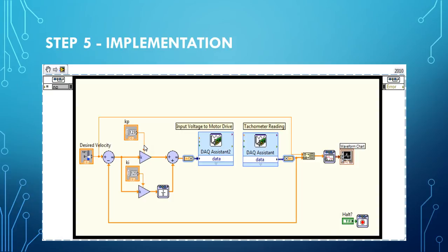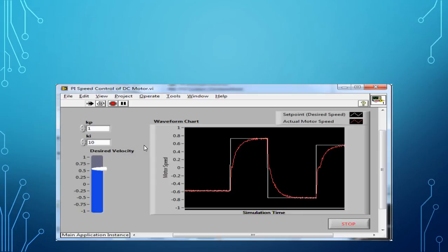Timing is an important consideration when using the LabVIEW control design and simulation loop with real hardware. Since the control design and simulation loop uses a built-in ODE solver with time steps, it is important to set the simulation parameters and the timing parameters of the loop to have the same time step. Data acquisition tasks typically use timing parameters, so it is also important to equate the simulation loop timing with the data acquisition timing.